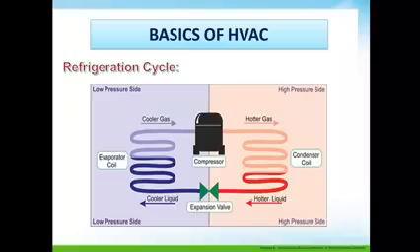The expansion valve, depending on the requirement, flows the cool liquid out, and it passes through the evaporator coil and again back to cool gas. The cool gas is passed through the compressor. The process of cooling happens at the evaporator coil, which is also known as the cooling coil.